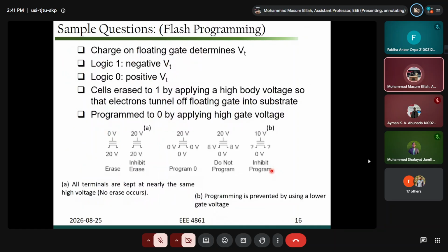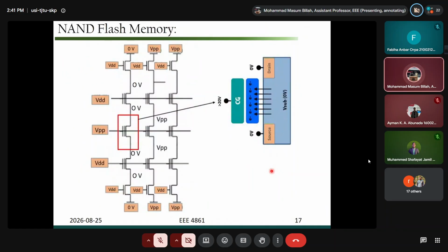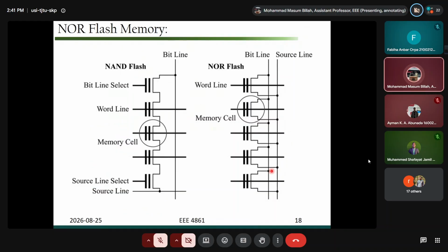So all together, like conventional RAM, ROM, PLAs, PLDs, application of PLDs, application of memory, memory access techniques like CAM or flash memory. So NAND memory, you remember NAND memory, NOR memory? One is serial, another is parallel. In NAND memory, you have transistors which are serially connected, so you have only one bit line and one source line. That's all. Very few interconnections needed.